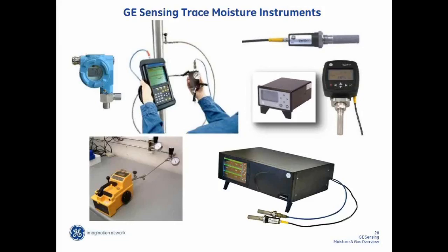The calibration system for our aluminum oxide sensors is a very automated process. We do thousands and thousands of calibrations. The sensors are ramped through 10 discrete dew points, but before we even do that, we dry everything out. And this complete process takes about a week to do.